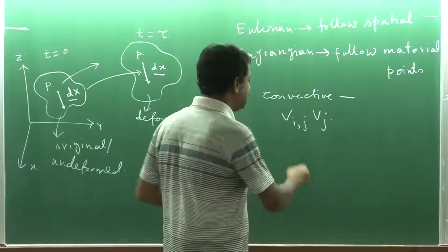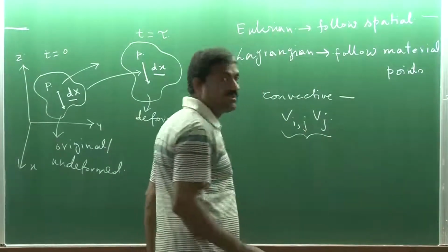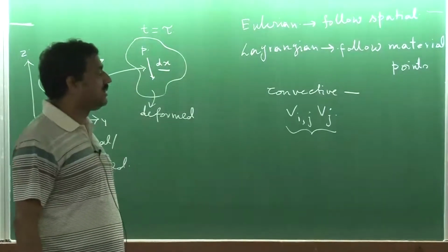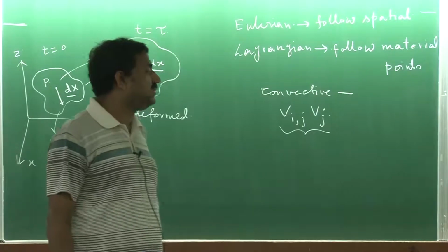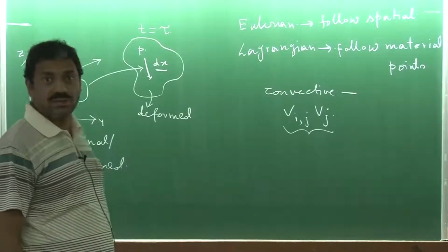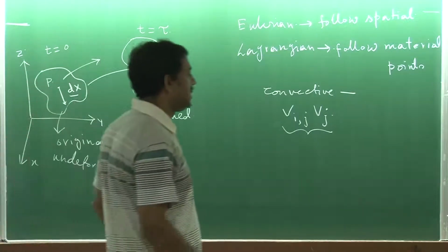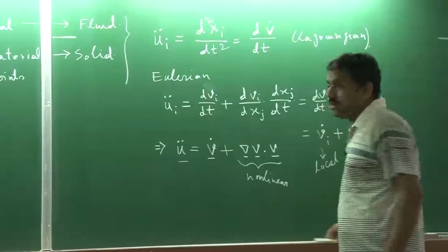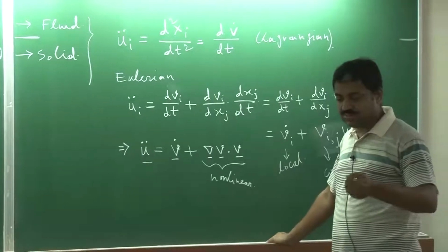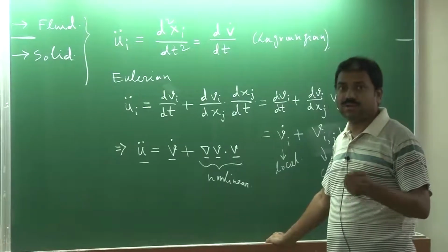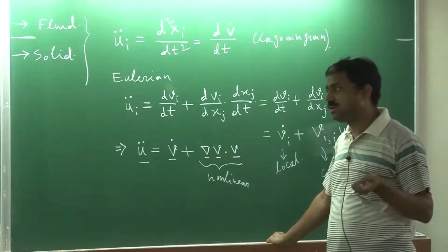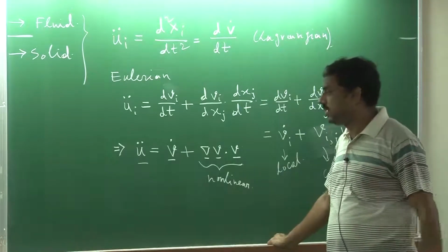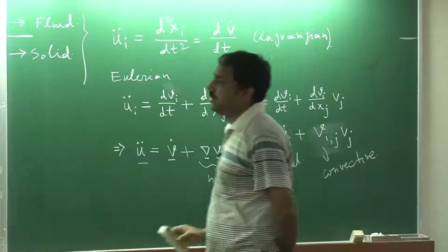So, we can see that this is non-linear, and from the very beginning, because of non-linearity, fluid mechanics becomes complicated, and that is what turbulence and all these kinds of things come from. So, this is the Eulerian description. Nevertheless, although we traditionally use Lagrangian for solids and Eulerian for fluids, either of them can definitely be applied for both. So, that is not a problem.